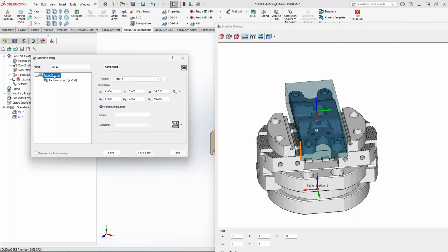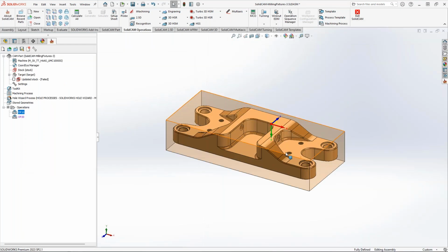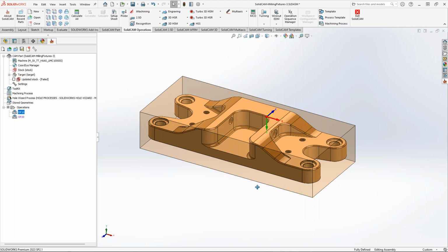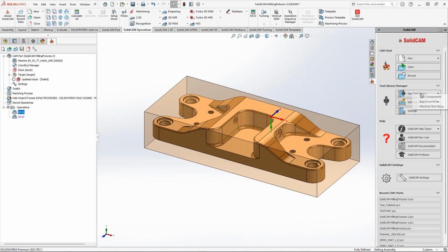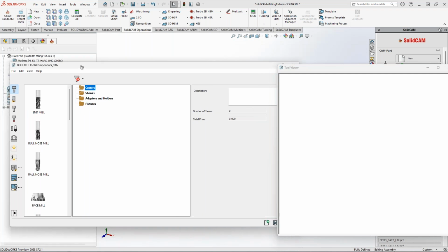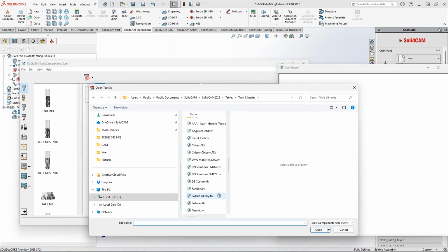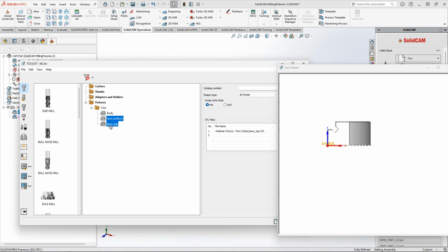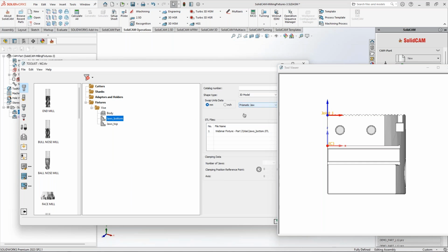I don't see my clampings? Did I? Oh, one very important thing I forgot to do. It's fine, because I want to show you that nobody is perfect, but there is some mistake that I made. When I go to tool components, I forgot to set that those components are jaws and not body. So jaws top and bottom, you can change it to be jaws, convert to jaws.